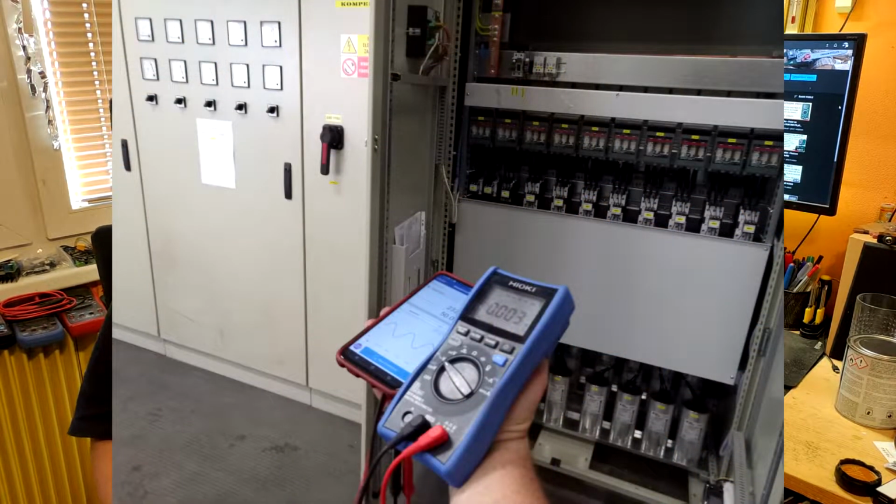Factories must have power factor correction. These are huge cabinets with capacitors that get connected to the network through contactors, and these contactors are controlled by a power factor regulator. Regulating power factor is a must because it lowers the apparent power consumption of a factory by even 30% if the factory is full of motors or transformers and such.